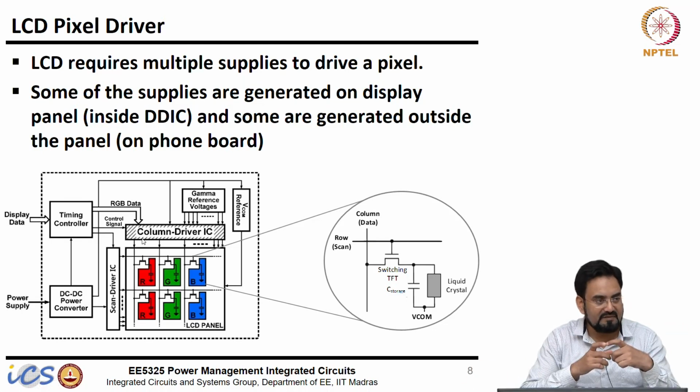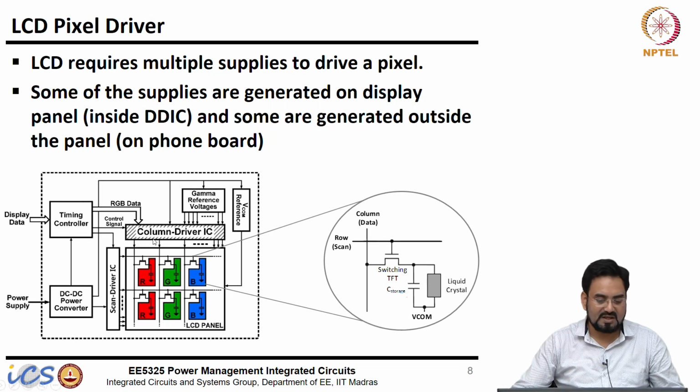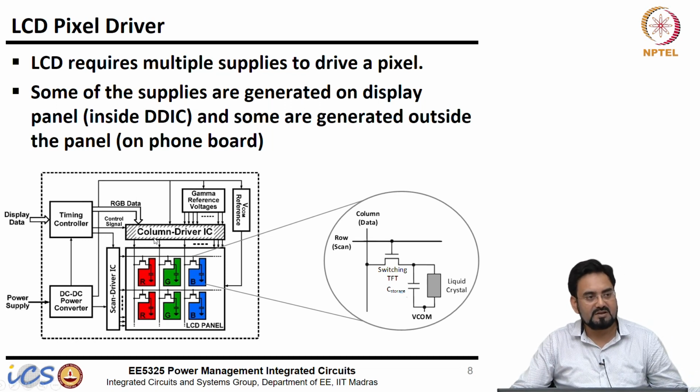In the panel you will have an LCD, your backlight, your polarizer, everything, and then everything will be mounted on a board, and on the same board you will have this display driver IC mounted, which will connect to your main board on the phone through your display cable, which is a flex cable.